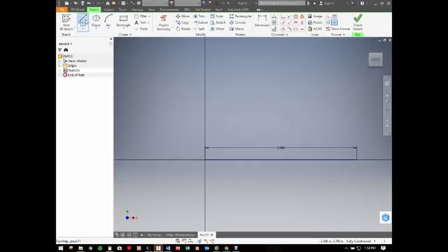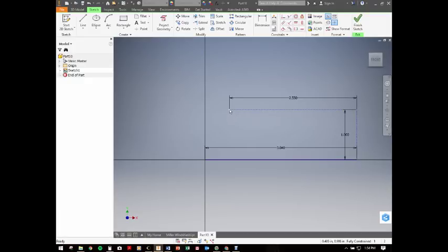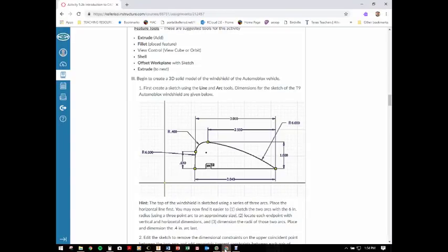So we're going to do a construction line. Make sure I start at that green dot that makes it contiguous. Going to go up 1 and then over 2.55. And all of that was just to be able to identify where that point is. I need one more construction line, and you'll note until I toggle this off, everything I make from this point, arcs, lines, shapes, are all going to be construction lines. This is 0.64, and I'm okay there. So let's go back to make sure I've got all those dimensions right. 0.64. So now I'm ready to start adding some arcs.